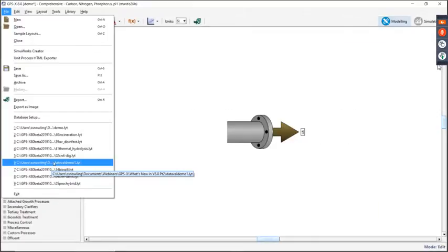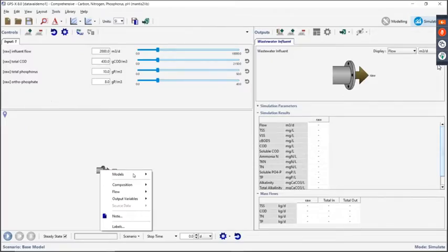But I want to check and make sure that all of the rows of that spreadsheet, all of the time steps where I'm reading in data, that they all make sense. It may be really hard to see, even if you take averages across all of your time steps, a spot where maybe there's a concentration problem just for a brief period of time. So what I can do is go to Influent Advisor and click on this data validation button down here.